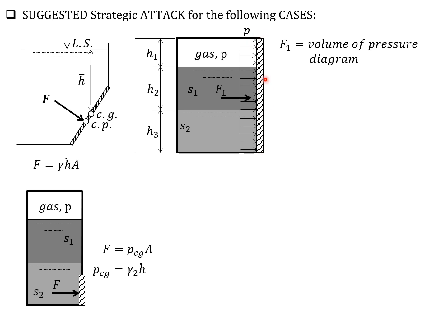So we assume that this gate, or this wall, is rectangular. So pressure times H, that's the area of this pressure diagram rectangle, then times B, which is the width perpendicular to the board, or perpendicular to this plane.